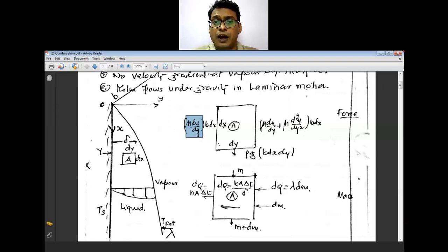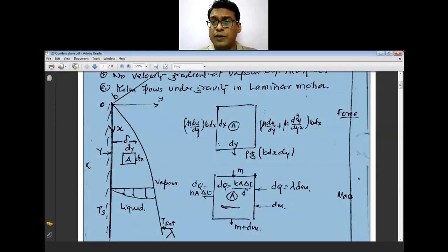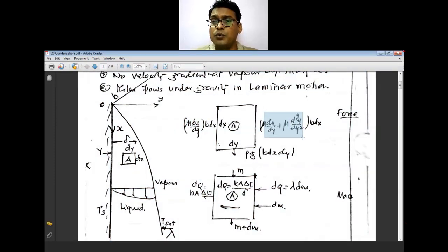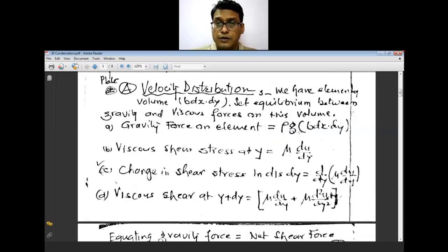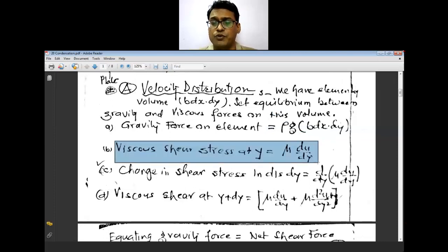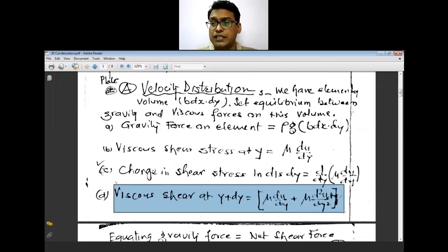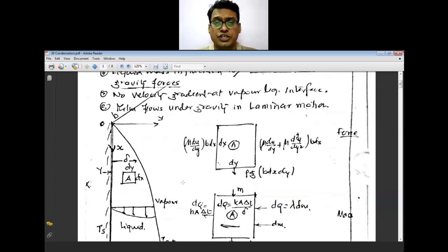And on the other side, the viscous shear stress at y plus dy is mu into du upon dy plus mu into d2u upon dy square.